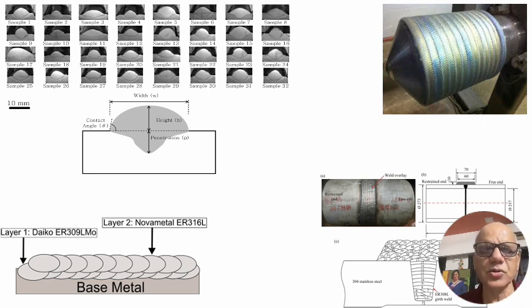Finally, the joint should look like this. That means you are going to have first a butt joint below it with number of layers and passes, narrow or regular, conventional, and on top of it, to have a good corrosion resistance, you are going to build up this additional material on top of the weld. So unless this weld is sound, your overlay will not be sound, and positioning layers and passes in this buttering or overlay also becomes very, very critical and important for us to really do it. So that's the importance which we give for the overlay.